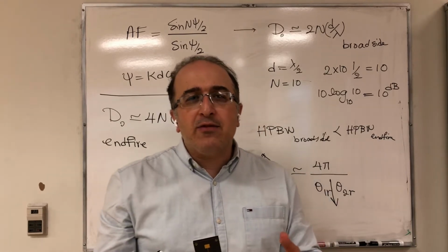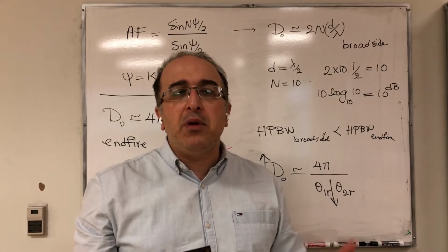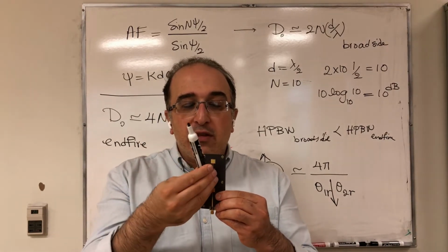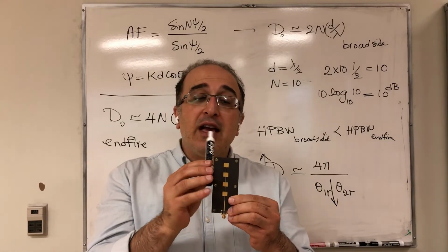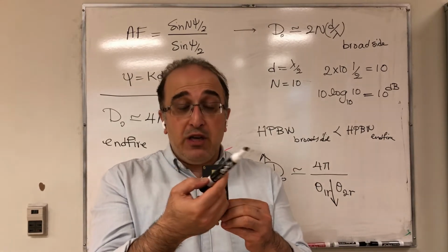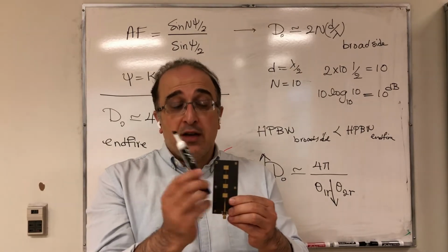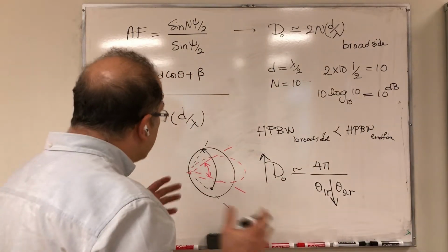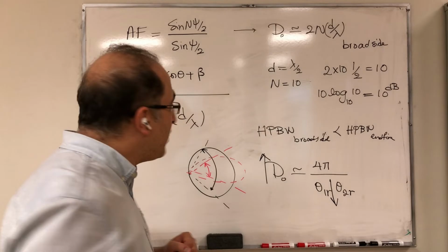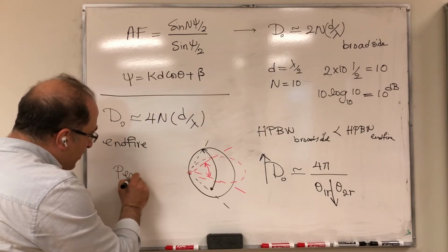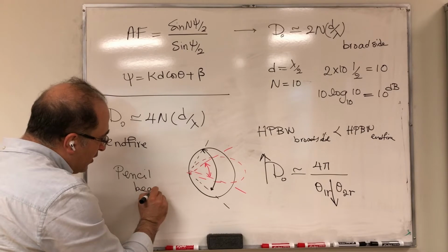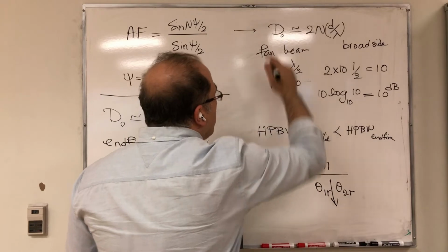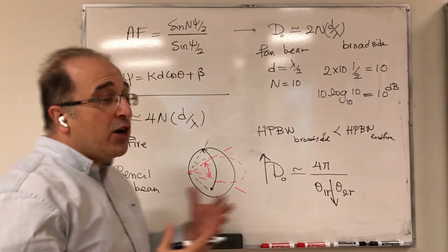And this is also correct when we are considering, for example, main beam as theta equal 30. So imagine this is theta equal 0, then you go theta equal 30, but theta equal 30 goes around the antenna and makes a fan beam, or a cone. So you see, we are not comparing exactly two similar sizes, similar types of patterns. So with here, we are thinking about pencil beam but with this, it's more fan beam. So we are not comparing them. We are not comparing the same thing.